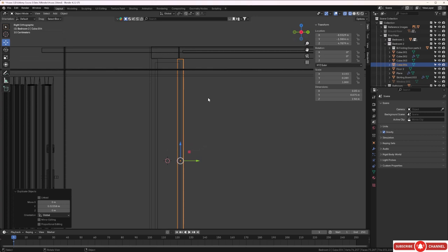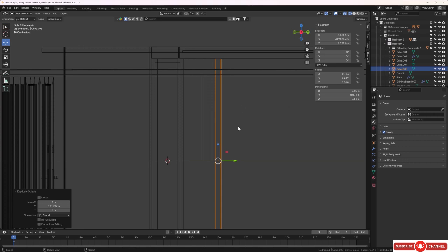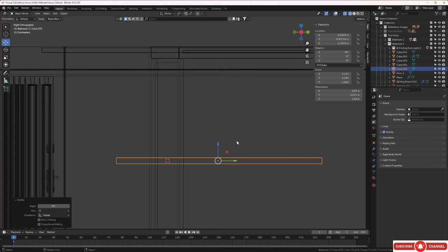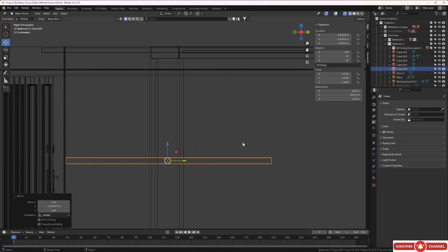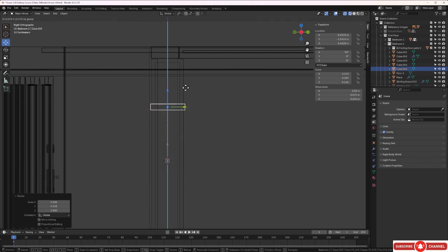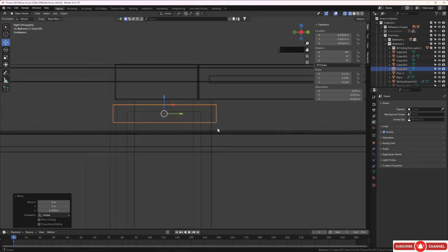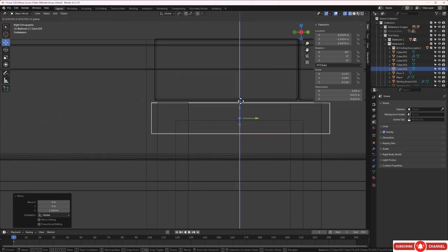Once we've done that, let's make a copy. So I'll press Shift D again and Y and bring that over like this. And I'm going to rotate this on the X axis. So RX 90, enter. And I'll bring this to the middle here like this, to the middle of that cursor. I'll now scale it down the Y, so I'll press S and Y, and just bring this in to something like that, and now take it up like this. Let's zoom in on this, and go ahead and take that up some more, until it's about there like that.